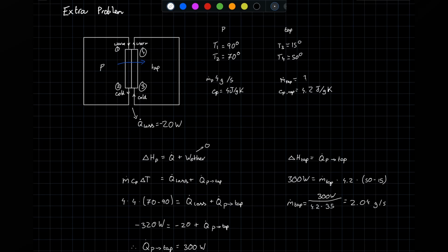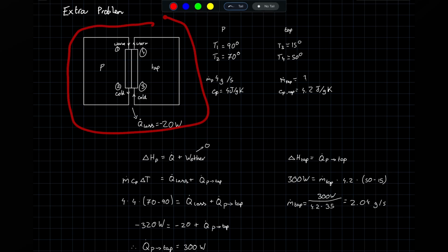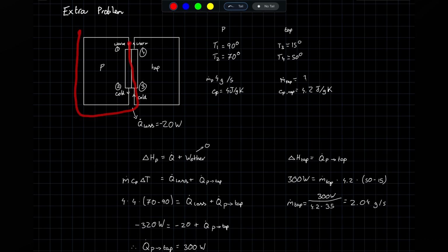So basically, whenever you have a heat exchanger problem, the easiest thing to do is to just work with the enthalpies, because if you look at your system as a whole, there is no energy change, which means in order to see an energy change, you need to subdivide it. And as soon as you do that, the energy flowing from one subsystem can only flow into your other subsystem, unless you've got some losses, but those are very easy to account for. You just add them there.